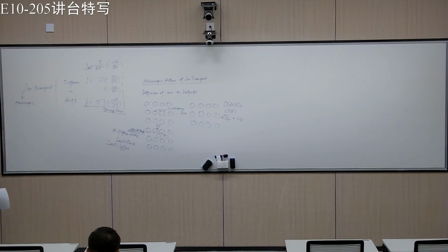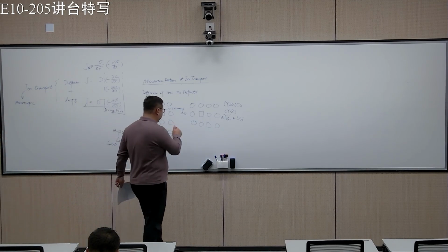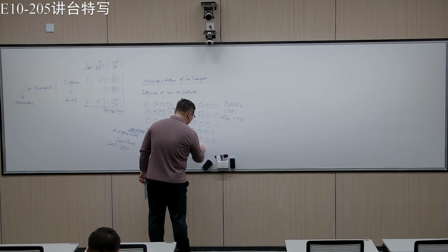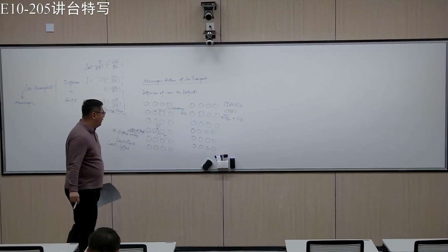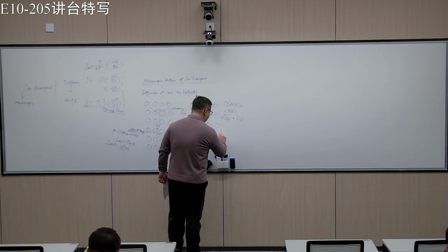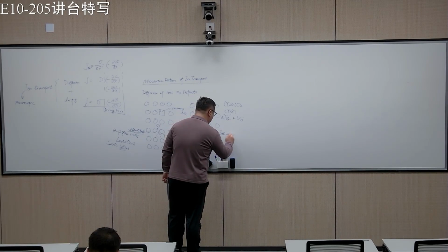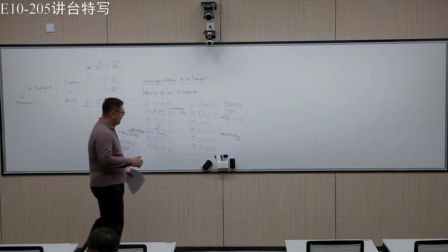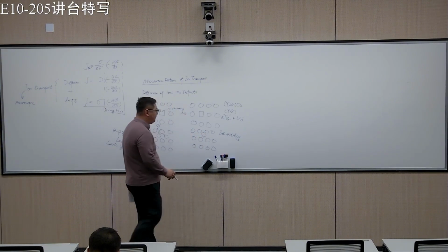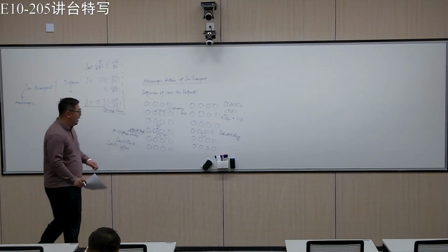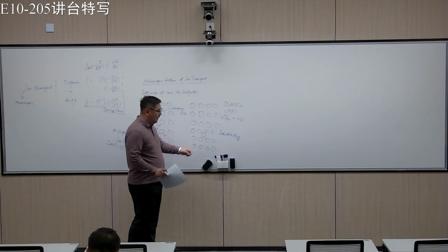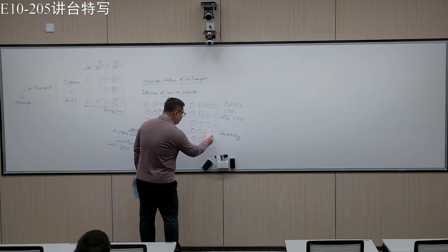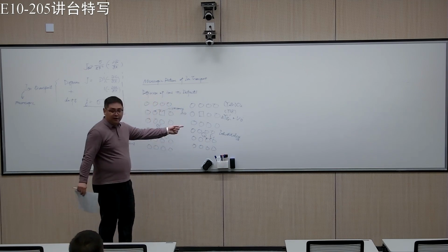Okay. So another very special case, what people found is the so-called interstitialcy. Okay. So it's different from interstitial. What it describes is a kind of concerted motion. Essentially, if you have an interstitial defect here, it can knock one ion, then move this ion to the interstitial site.